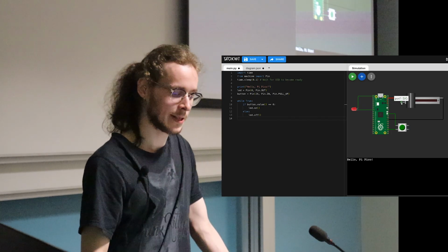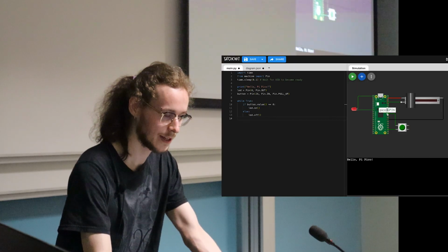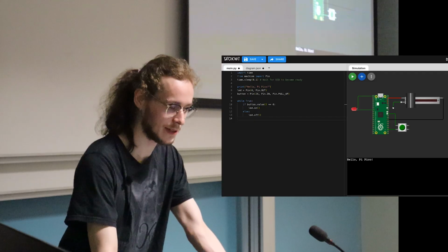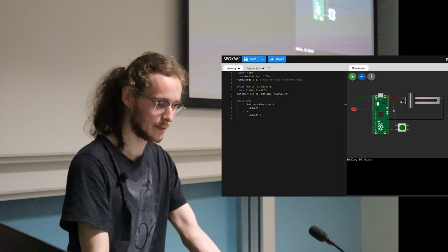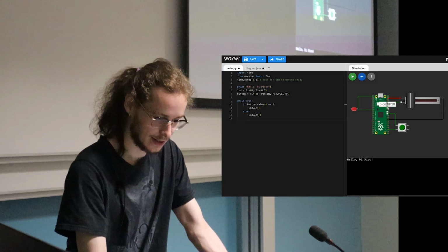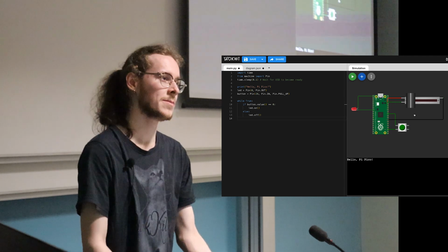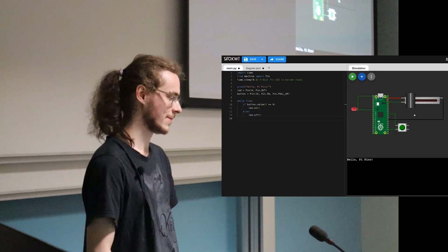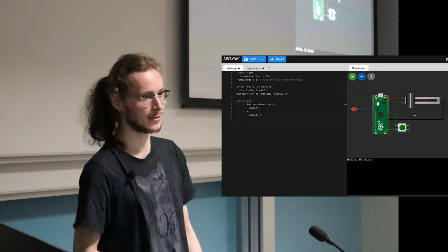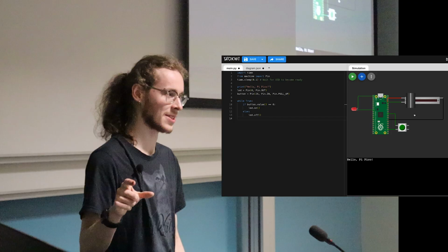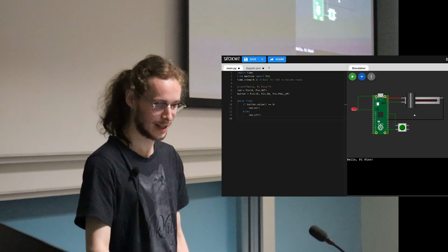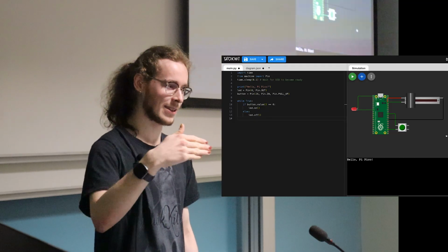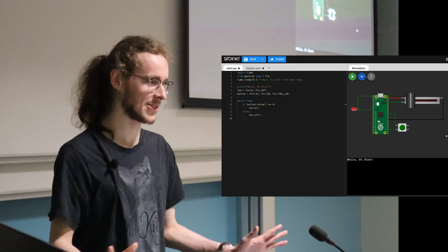When we click on this, it already highlights which of the pins are analog pins. So the Pico only has these pins as analog pins. And some microcontrollers don't have analog pins at all, so you'll need an analog to digital converter, which is just another circuit that will convert it. It'll be like a little teeny square, and you connect one end into it and the other end's digital, magically.